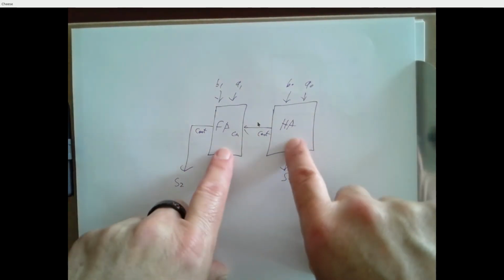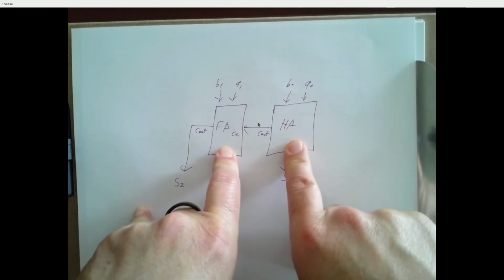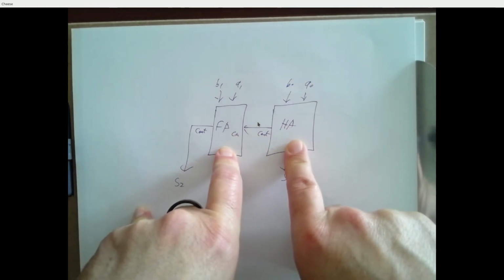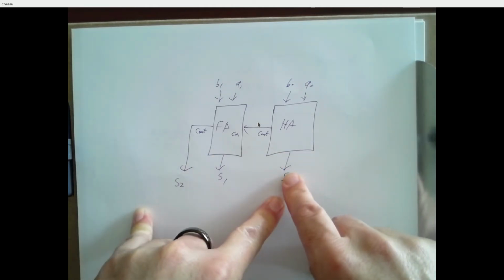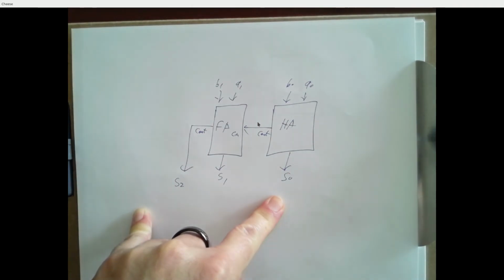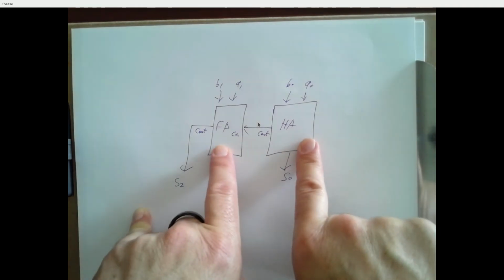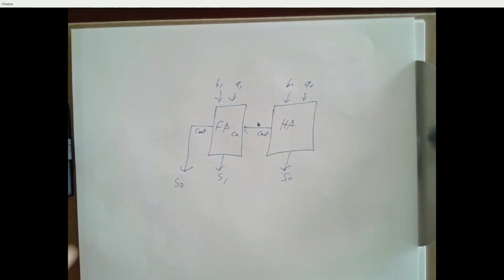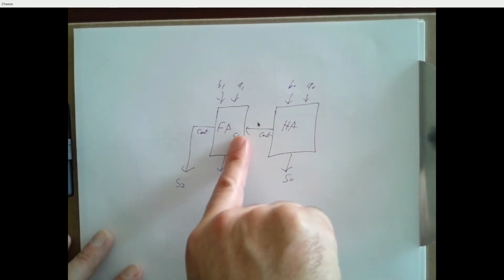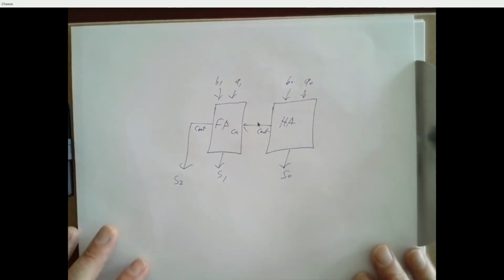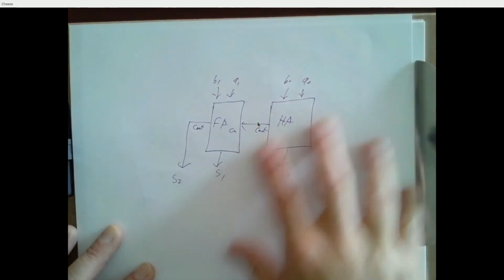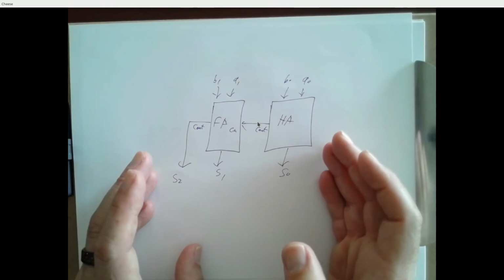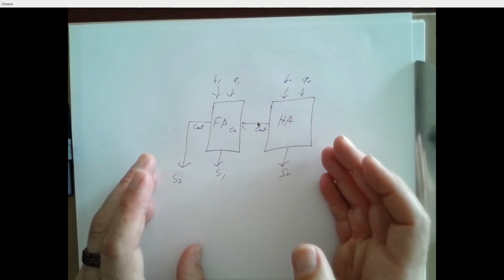Now you've got to implement these things. How do you do that? Write a truth table. Write down the sum of products. Use a K-map to simplify. Draw a wiring diagram. You've got to go through all those steps. If you do that, you end up with a way to implement this and this, put them together, either in one big diagram or label this output and label an input on this diagram with the same label. Put on pin numbers, part numbers, and then you've got a wiring diagram based on this. Build that, test it. Is that clear?